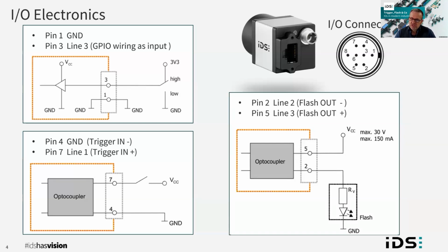The electronics also differ in terms of whether, for example, optoelectronic decoupling is integrated to protect the internal electronics of a camera, if a differential signal with a higher voltage is used to optimize the signal quality, or if you want to use direct wiring with a 5-volt TTL level for a signal exchange. All of these circuit variants have their advantages and drawbacks in terms of signal delay, protective circuitry, shielding, robustness, latency, or functionality.